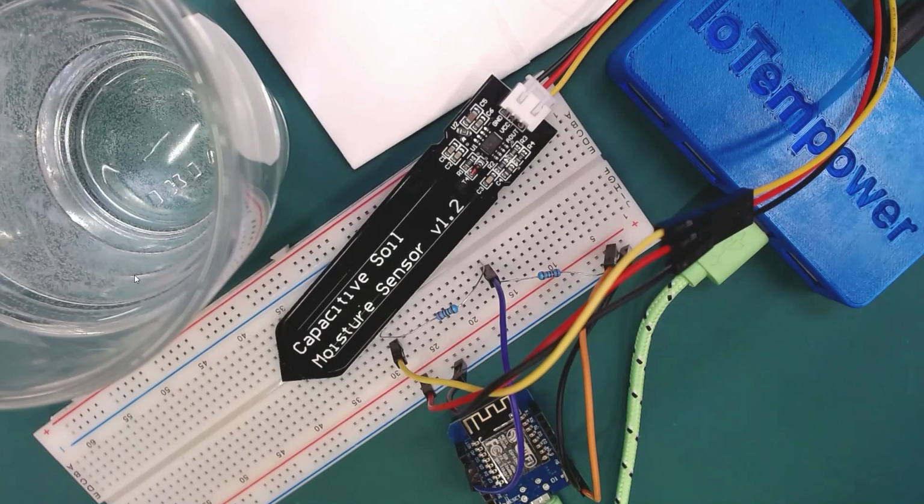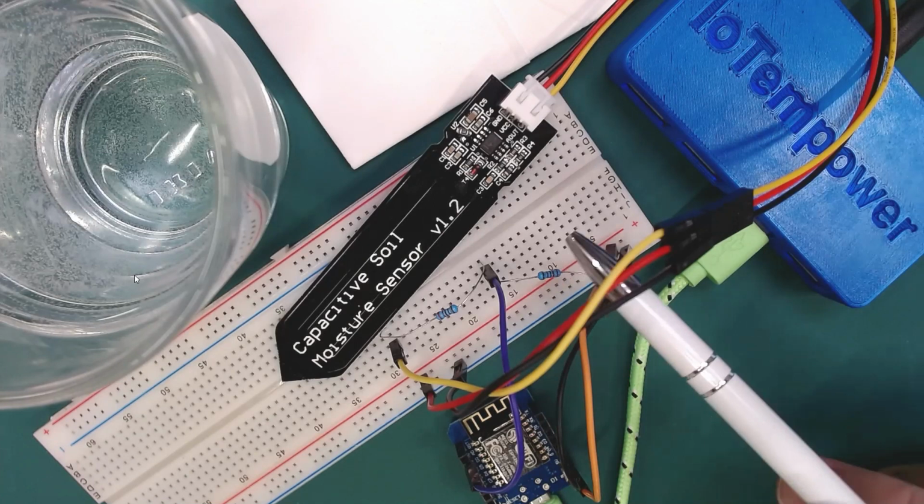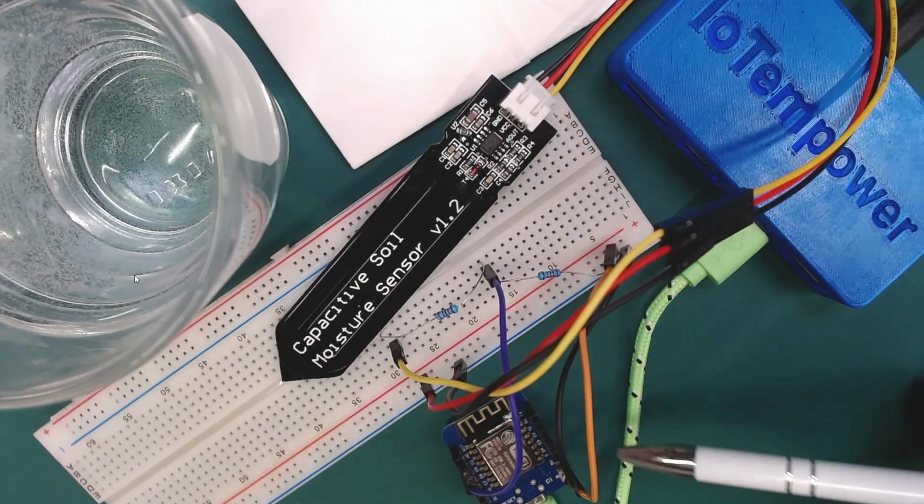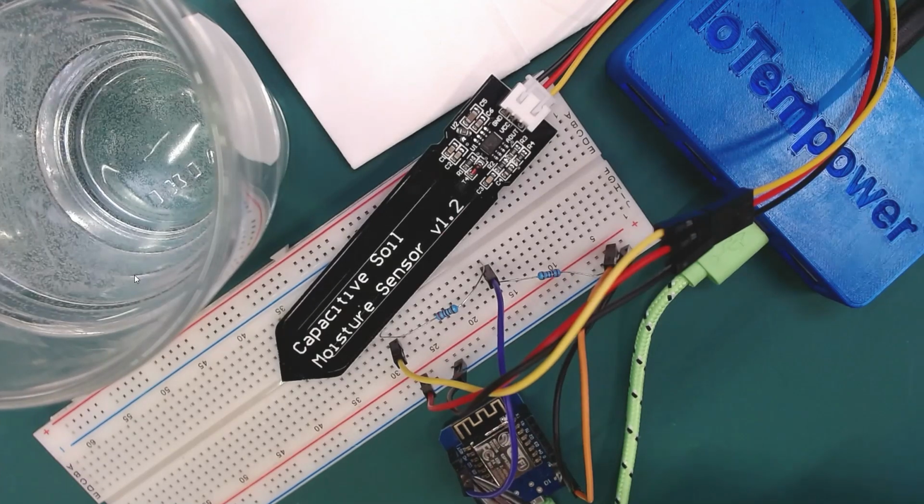So you see here a capacitive soil moisture sensor. This sensor is actually connected via a voltage divider to the A0 port here of the Wemos D1 Mini. So basically we measure voltages between 0 and 1 volt there to see later if this is wet or not. But of course we don't know which values we actually get, so I do know that if we don't use the voltage divider, we get values that are too high, so that's why I use the voltage divider